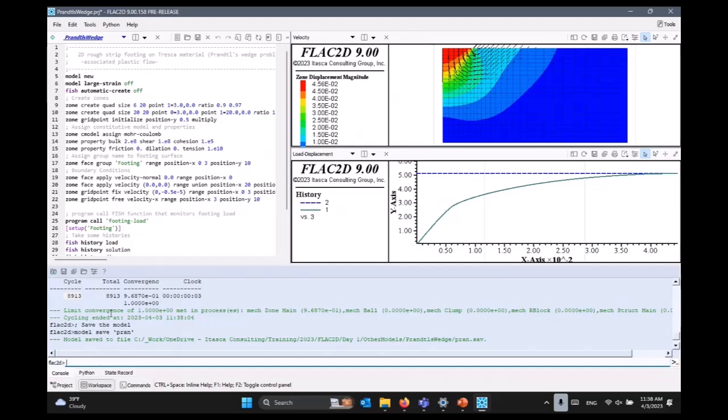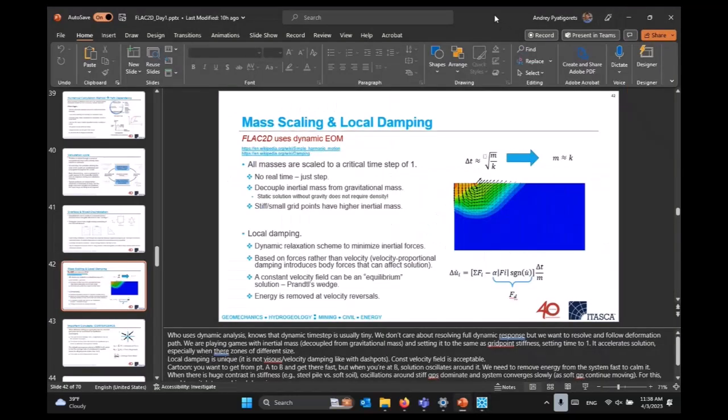So for the calculations where you expect large plastic deformations, kind of unbounded plastic deformations, where they don't expect to stop essentially, material continues to deform plastically, you can use a different type of damping, which is combined damping. But in reality, it's rarely used because there are not so many problems like that. If you get failure, you already know that your engineering or your model failed. There's no need to continue calculating it.